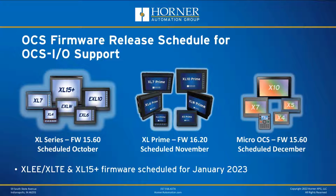If there are multiple bases, it will report back what UUIDs it sees, and then will let you assign them to which node ID order you want based on your program. So that's if you're using multiple racks. Really, there's no physical dials or anything to set a CAN ID. You would just have to be mindful in the programming side of setting different node IDs other than what you use on, say, smart sticks or smart rail units that require a physical CAN ID. You would just change that in software, and I believe Cscape flags you if you have duplicate IDs anyway.